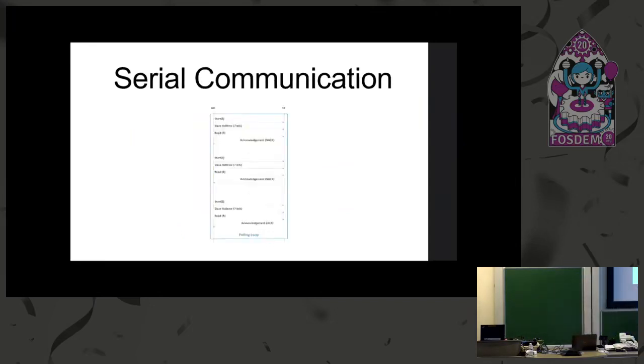And I did just mention serial protocols for transferring information in and out of the secure element. That usually happens over I2C, and this is another example of the I2C. What's the name of this UML diagram? It's called a sequence diagram. Thank you. So we have on the right the secure element, and the HD on the left, that's the host device, which is sending information back and forth. You can consider this to be an MCU, for example.